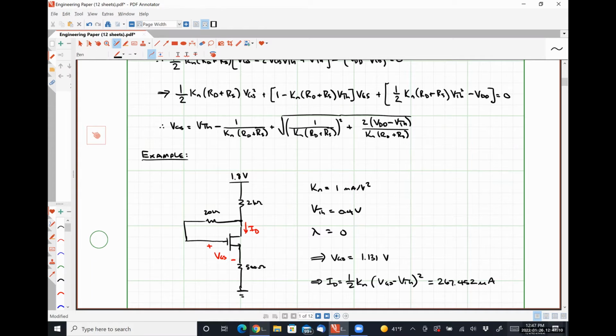All right, so I hope it's obvious. We do not need to set up a system of equations or anything for triode region operation because this circuit is literally incapable of operating in that mode. So our next step here is going to be reanalyzing this circuit with channel length modulation effects present. Now, this isn't going to be particularly difficult analysis because it's literally this exact same analysis, except that we now have a channel length modulation coefficient in the mix.